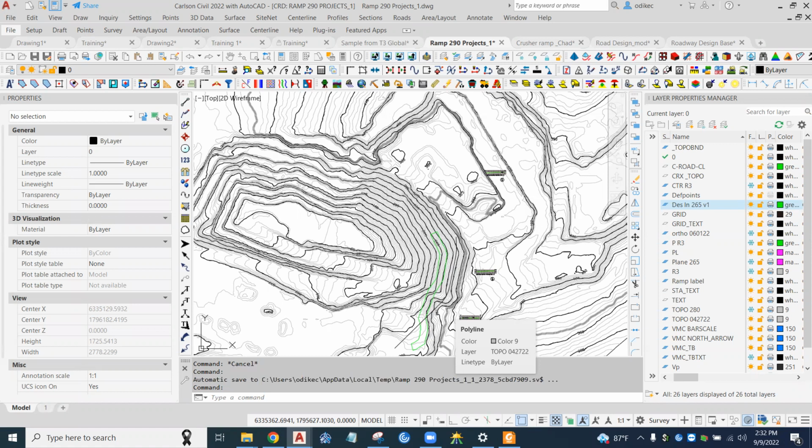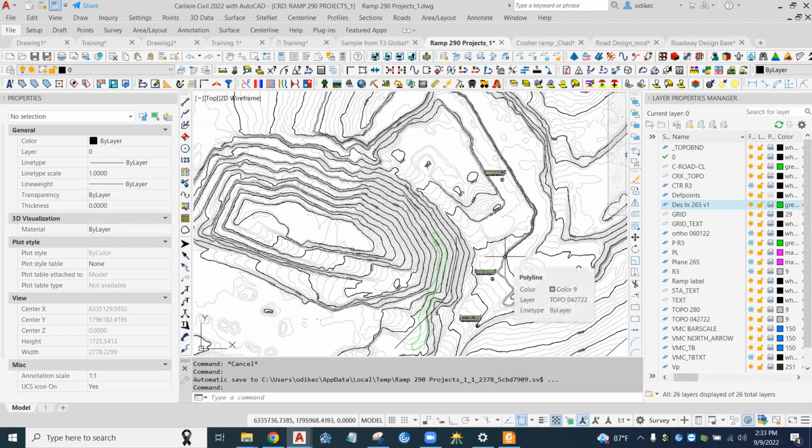Yeah. The way I was able to do it was I created a plane that intersected the wall, from here to here. I just created a line from 265 to 365 and did a multiple offset of that line, but it was just the same slope. And I just intersected this one versus that one. I got that line, which I was using as my profile from there.